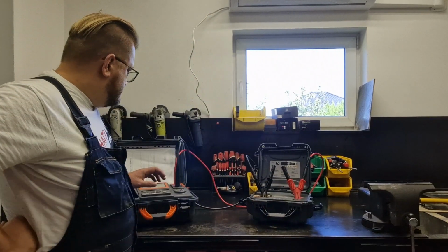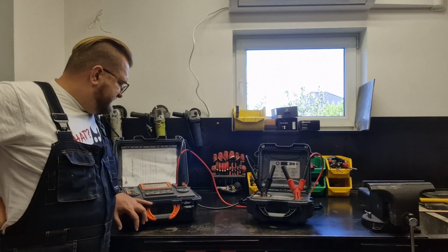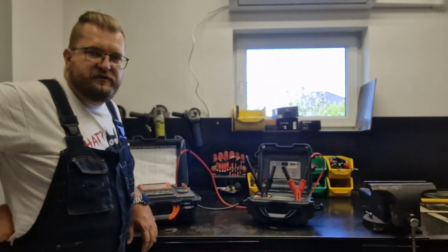Welcome to my garage. In this video I would like to show you one very interesting method of diagnostics of the insulation for cables, which is the partial discharge indicator, available in the SONEL MIC-15k1 meter. So this is a 15 kV insulation resistance meter. For meters manufactured before 2023, it's required to do a firmware update to have this feature.